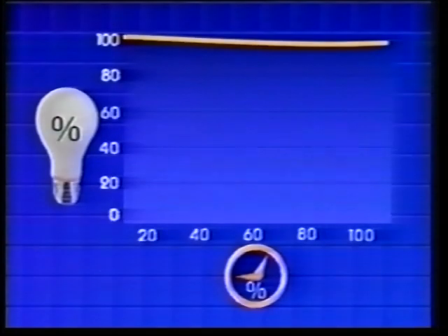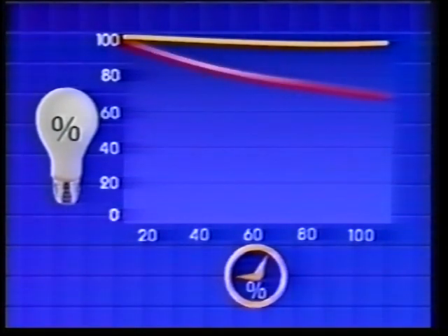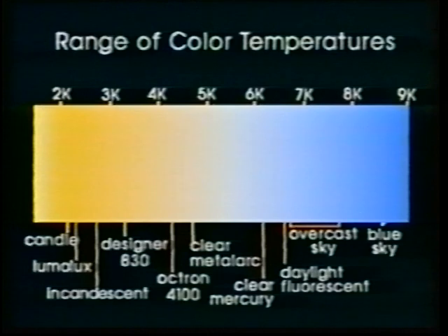That's much hotter than a normal incandescent lamp, and the bulb has to be manufactured of quartz glass to withstand the temperature. Another benefit of the tungsten halogen lamp is that it maintains its lumen output over its entire life. A normal incandescent lamp loses light output due to blackening, but the cleaning process of the halogen cycle ensures a steady output with a tungsten halogen lamp. The quality of light from a halogen lamp is also different. Most tungsten halogen lamps are designed to burn at approximately 3,000 degrees Kelvin. That's somewhat higher than normal incandescent lamps, which means that the light is whiter.